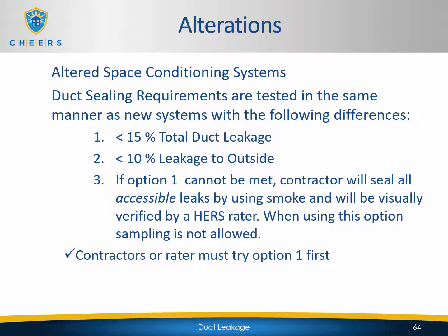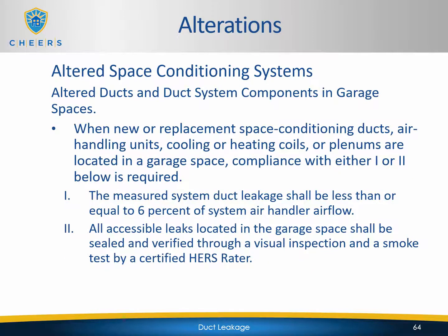Now the contractors do need to try and achieve option one first, try to hit that 15% total leakage. If they can't achieve that, then they can move on to doing the smoke test itself. Altered systems that have ducts or duct system components in the garage are going to be treated a little bit differently, and they're going to have different pass-fail criteria.